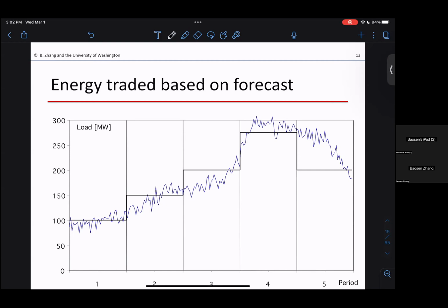So if you increase this to 15 minutes, you may not be able to solve this optimization within a day. Even at hourly dispatch, most optimizations take several hours to solve. It takes your computer several hours to solve this problem. If you go to 15 minutes, you can't finish solving this problem in time. So there's a computational limitation. That's something to remember. A lot of this comes down to being able to solve the optimization problem, technically. So this is a limitation coming from there.